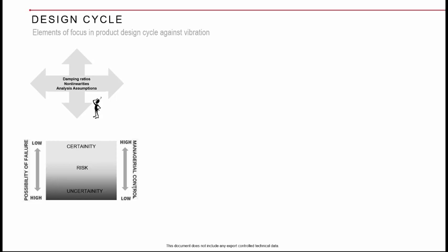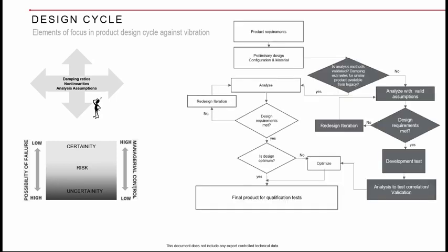Okay. So again, the boundary conditions, how you can consider them. Maybe something can be considered as a bonded contact at lower excitation levels, but for higher excitation levels, they may slip. Then you may have to consider a certain stiffness parameter to model that effect. So when you don't understand all these, your predictions are subjected to a lot of uncertainty and you cannot take any decisions. So that is where we have to be focusing in our design cycles.